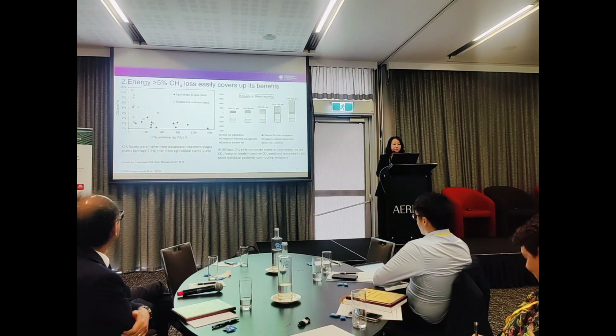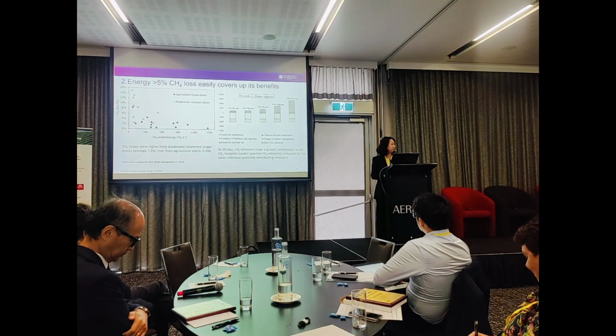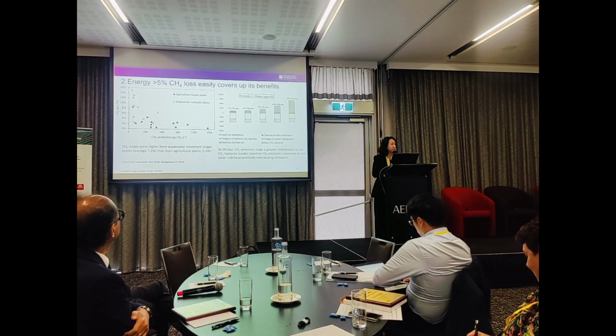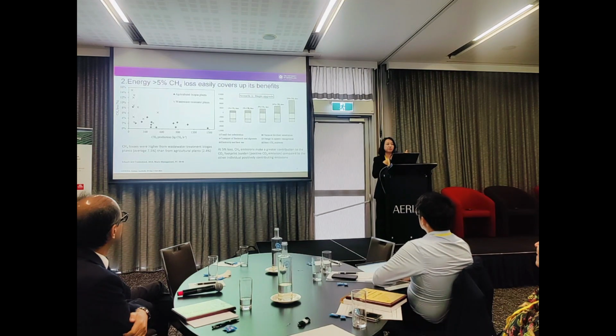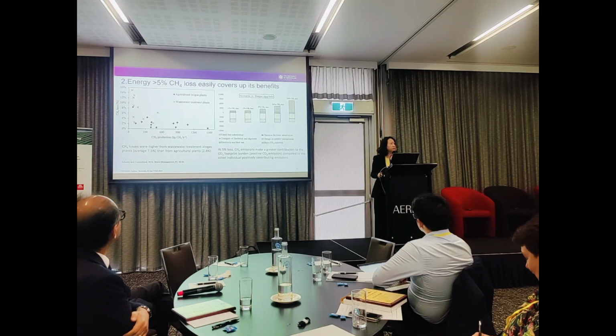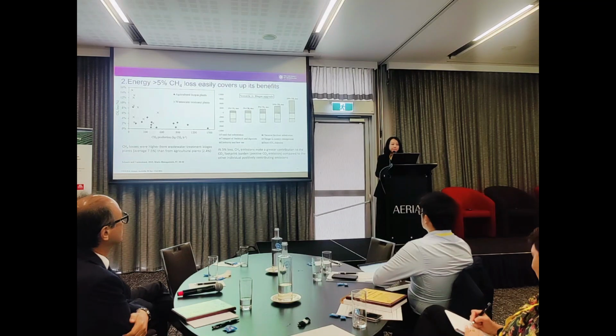Okay, before that, I want to mention the reasons methane leaks a lot. One reason is that many of the anaerobic digesters we use are the floating hood type. That's one of the big sources. The other is the pressure relief valve for safety, which has also been identified as a hot spot for methane release. Those are simple things, and later we can consider simple engineering solutions to stop the leakage. That's going to be brilliant when we look at energy recovery.